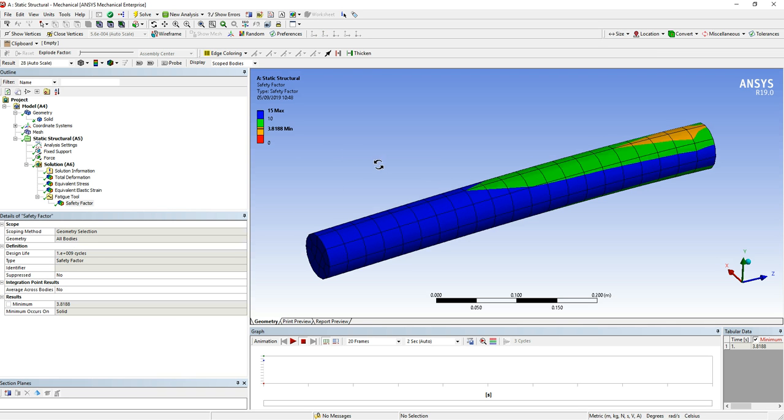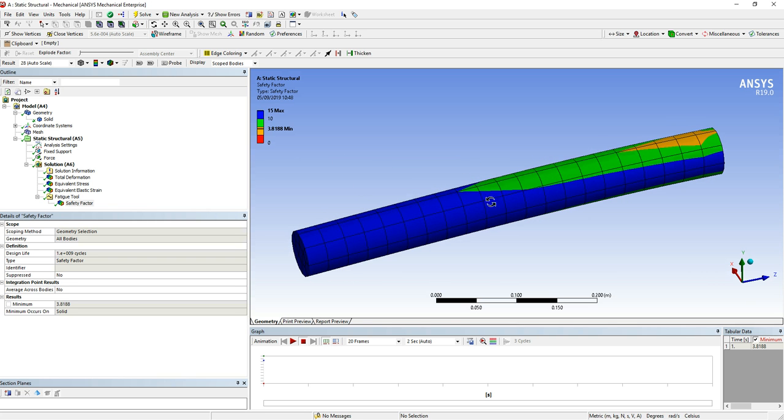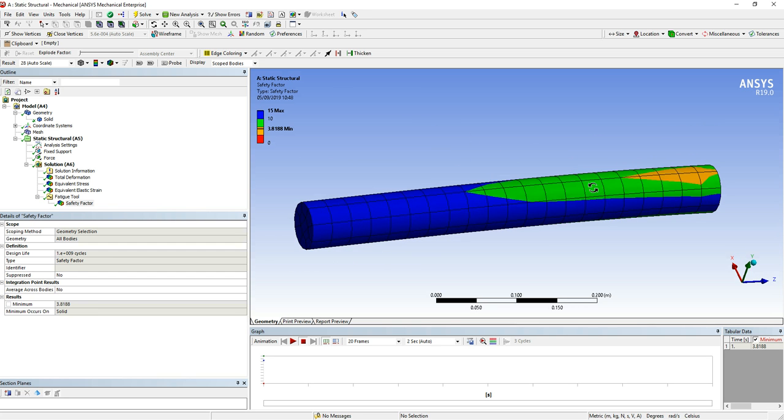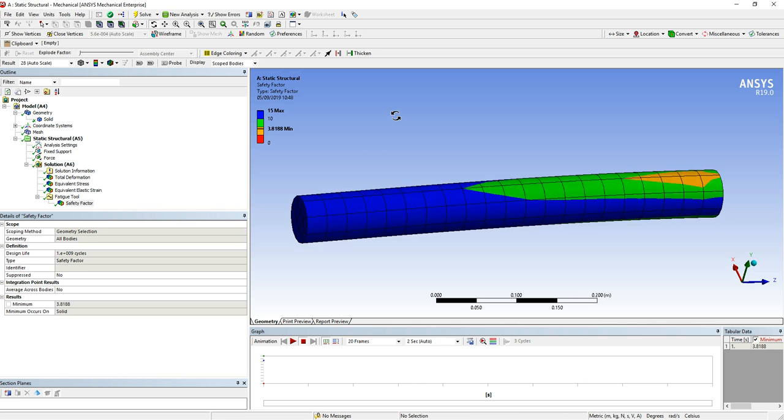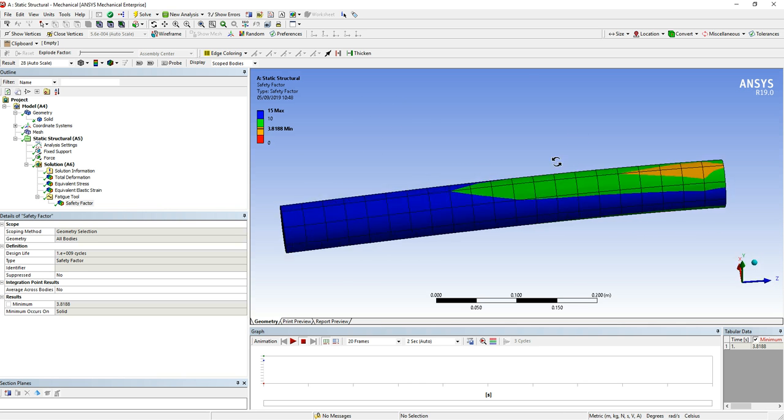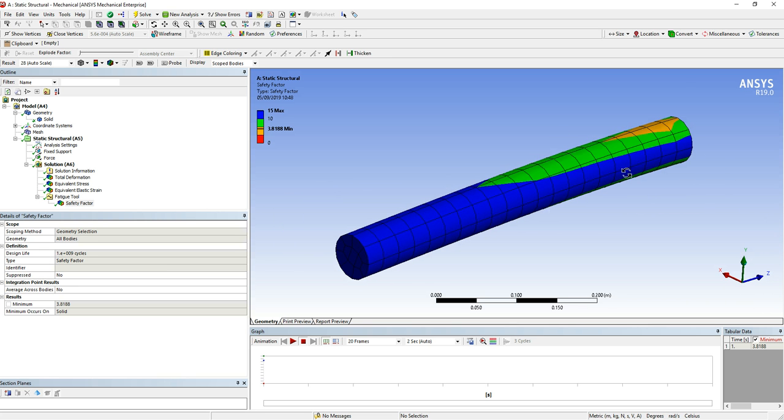Now we notice here, the safety factor in this case, when it's at a solid state, comes back as 15. Our initial calculations came back at around 14.3. It's because the mesh is so clumsy at the moment, there's going to be quite a large error between the two. When the component goes through its overall, we actually get a performance of 3.8. So the maximum is 15 and the minimum is 3.8118. Anything below 1 is a failure and should not be pushed forwards.